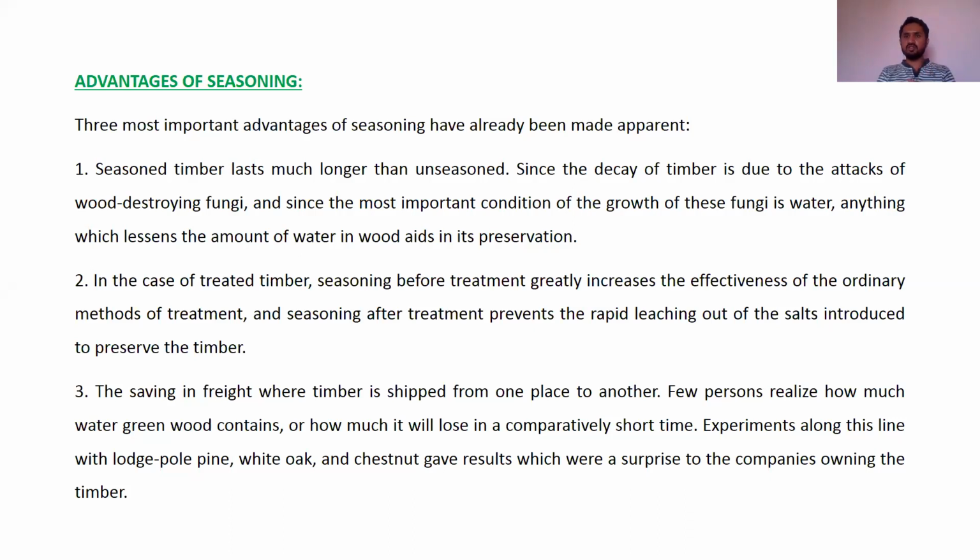That is the advantage of seasoning. Second advantage, in the case of treated timber, seasoning before the treatment greatly increases the effectiveness of the ordinary method of treatment, and the seasoning after treatment prevents the rapid leaching out of the salt introduced to preserve the timber.